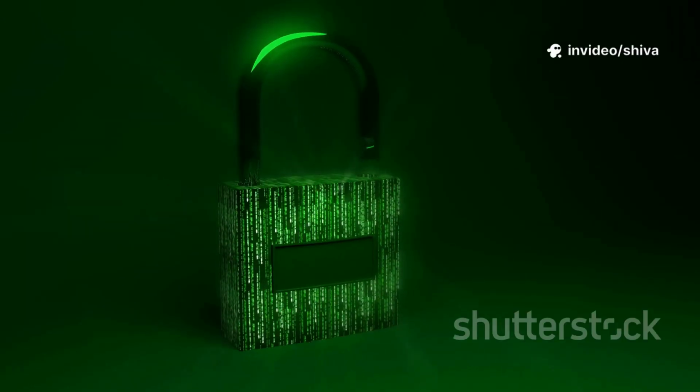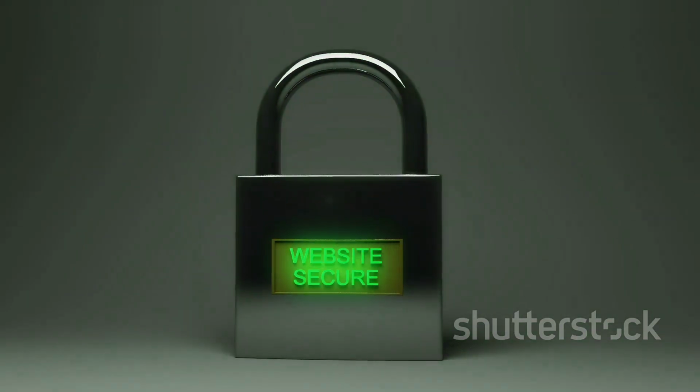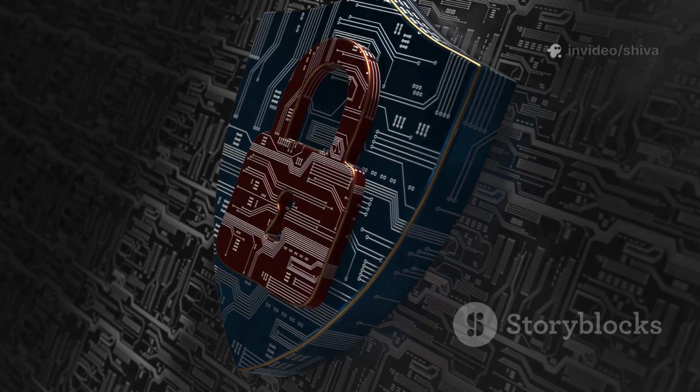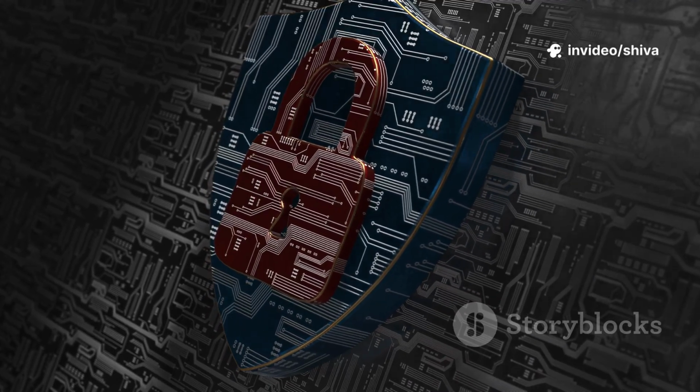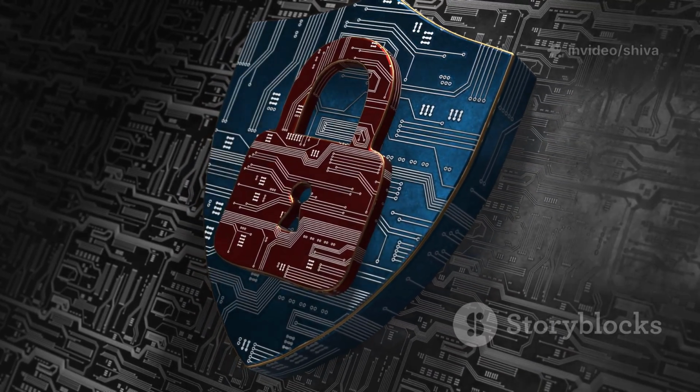Then there's the AND gate. Imagine a door with two locks. To open the door, get a 1 as output, you need to unlock both lock 1 and lock 2. If only one lock is undone, or neither is, the door stays shut and you get a 0. An AND gate needs two inputs to be 1 for its output to be 1.